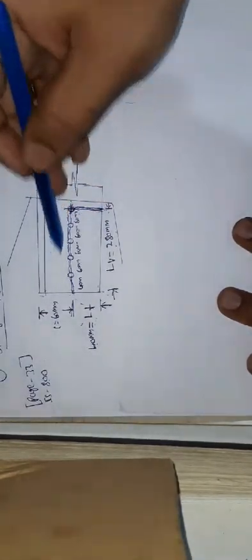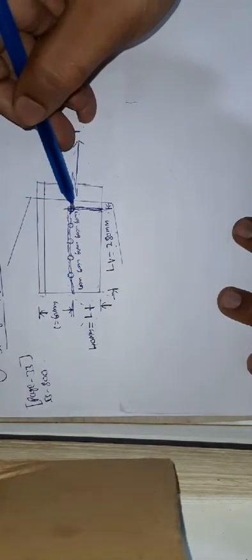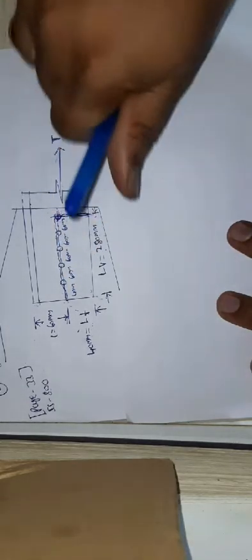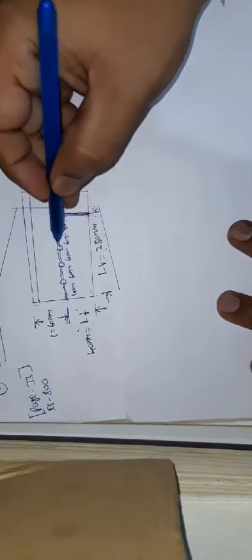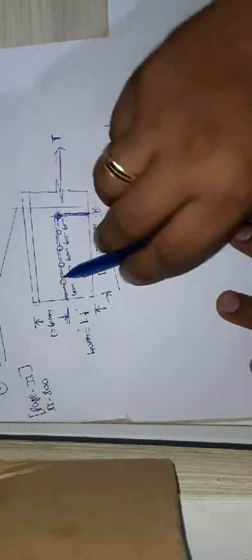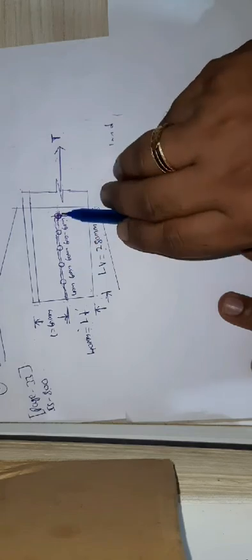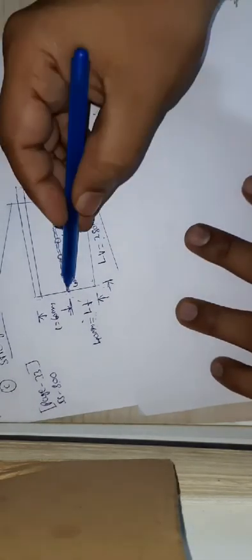That is what I explained here. When you apply a load, it will tend to shear along this line, and this line is subjected to tension. This is a shear line. It is subjected to shear along this line, so it is also called the shear line. The length of the shear line is 280 mm: from here to here is 240 mm, and adding the remaining edge distance it will be 280 mm.